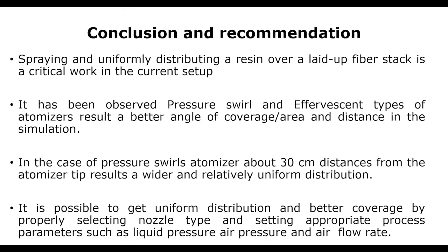When I come to the conclusion and recommendation, spraying and uniformly distributing resin over a laid-up fiber stack is critical work in the current setup. That means the setup which we are developing. It has been observed that the pressure swirl and effervescent type of atomizer results in a better angle of coverage or area and distance in the simulation. In the case of the pressure swirl atomizer, about 30 centimeter distance from the atomizer tip results in a wider and relatively uniform distribution.